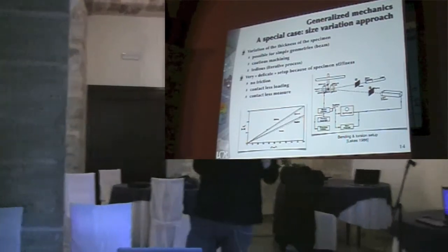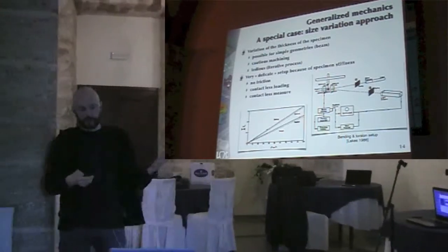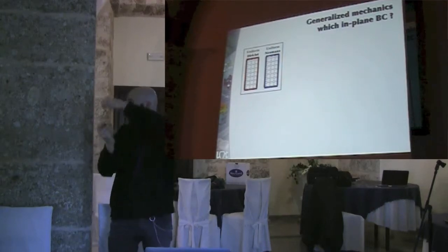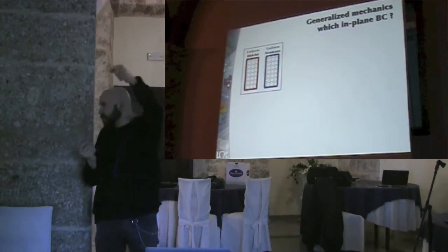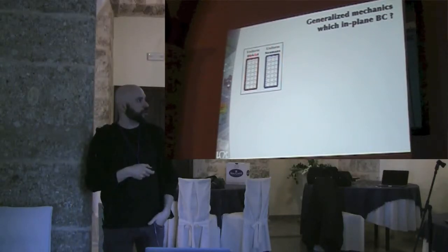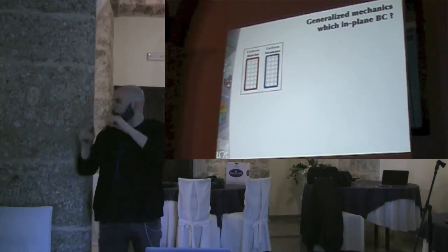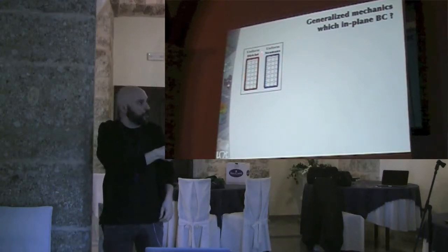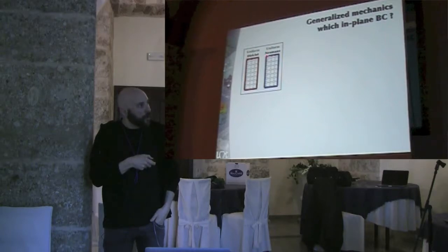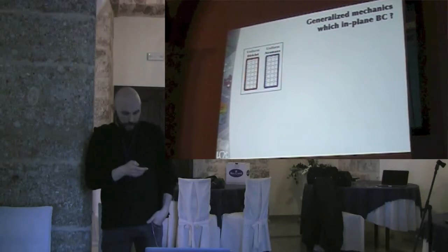But this is a very special case, but at least it was interesting to show you because it's quite amazing. So, if you want to apply boundary conditions and perform a test, a shear test, tensile test, or whatever, what can you do? Usually you can choose between what I would say uniform, that is to say rigid body motion displacement of the upper part or the sides or lower parts, or a uniform Neumann, that is to say homogeneous force applied there or there or there or there.